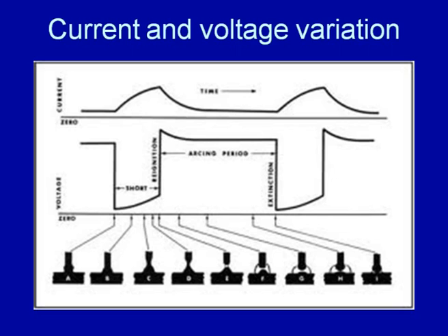So, there is an abrupt decrease in the voltage, and thereafter the welding current starts to increase. In this process of the increase and decrease of the welding current, when there is a short circuiting, there will be an increase in welding current and a decrease in arc voltage. This kind of cycle keeps on repeating